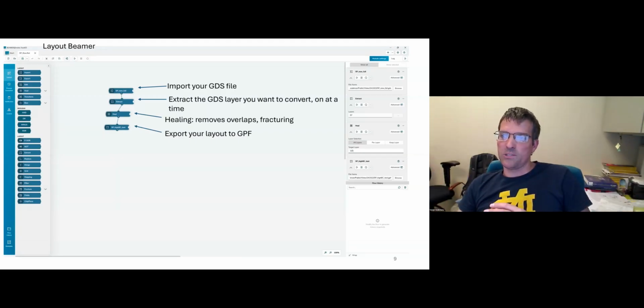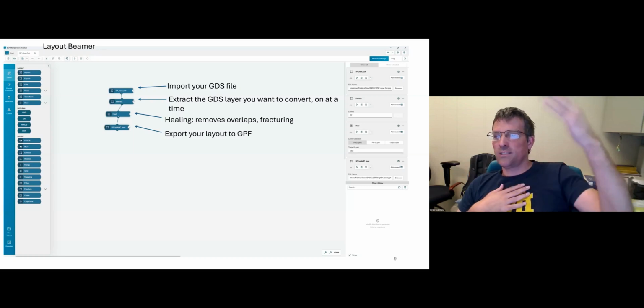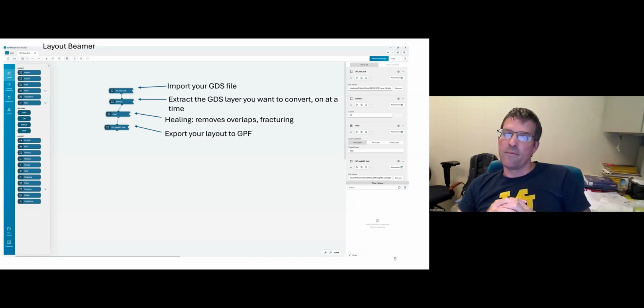So for example, if you make some junctions, transistors, or something else, you cannot just do one single layer. And sometimes you even have to work with an optical, lithographically fabricated bonding pad structure, and then fabricate your nanoscale devices on the chip. So usually you have to extract the layer which you want to expose.